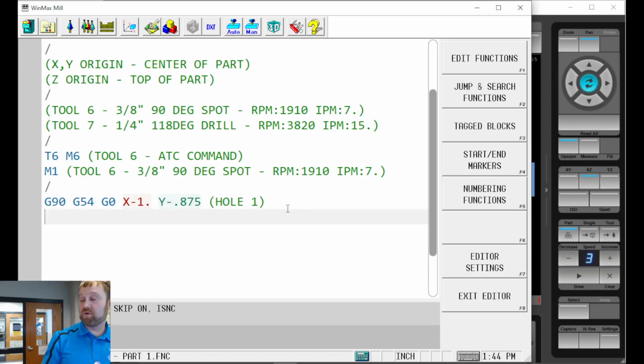So those that have programmed the CNC before are going to find out that this control is really nice on that too. If there is an error, on the mill especially, it'll pretty much jump to where the error is and isolate it to one line. If you've programmed on other controls, it'll tell you there's an error, but it doesn't take you right to it. It just basically says you got a problem in your program somewhere, and then you got to sit there and go line by line. I love that about this control, especially for this first year manual programming class.